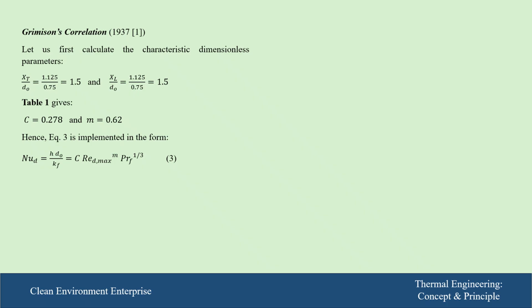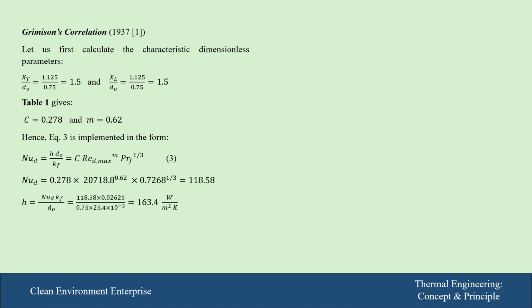Of course, equation 3 as presented can be used to get the Nusselt number equal to 118.58, and with the definition of Nusselt number, we may get the heat transfer coefficient of air to be 163.4 watt per meter square Kelvin.